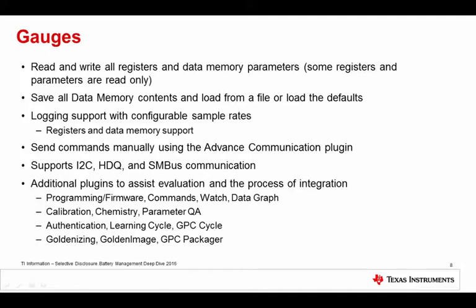So you can update the firmware, for example, the programming firmware commands. Or there's a commands plugin for doing things like seal and unseal and sleep and so on, issuing straightforward commands to the gauge. Watch and data graph plugins let you watch and graph specific parameters or registers along the way so you can see what's happening in the system.